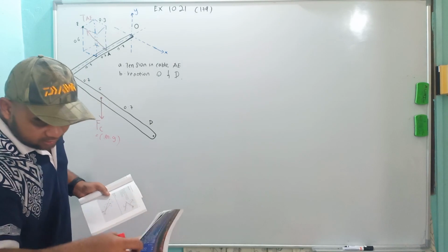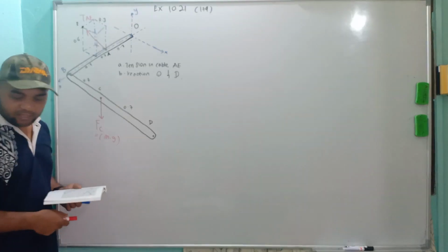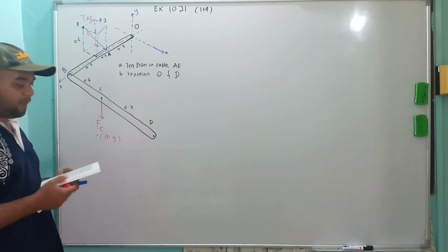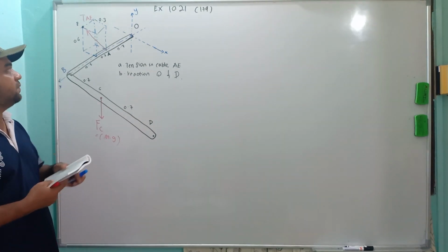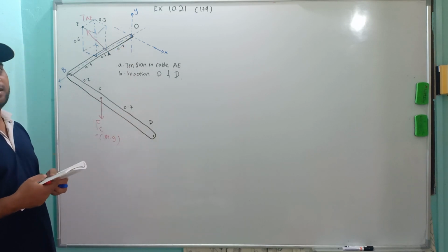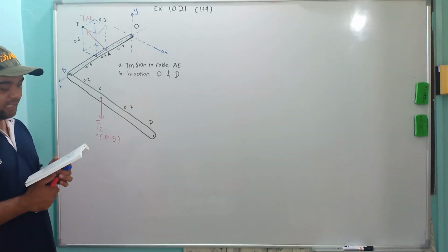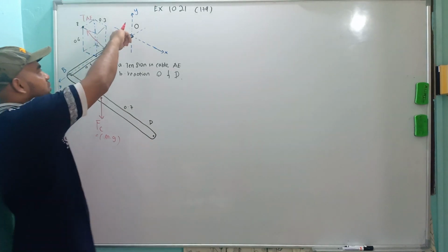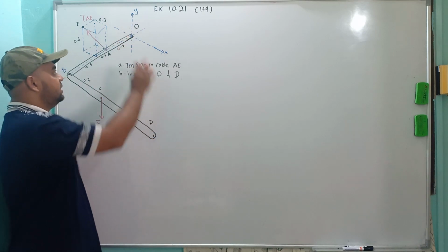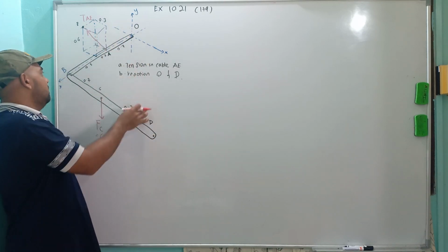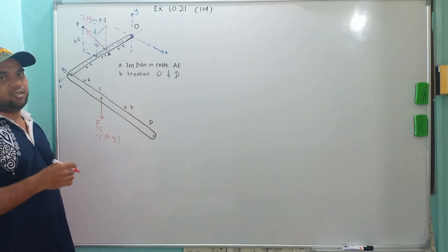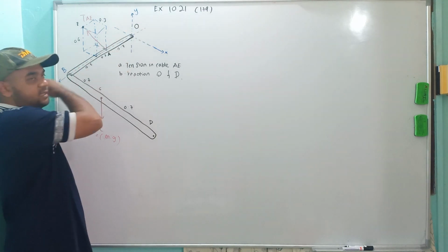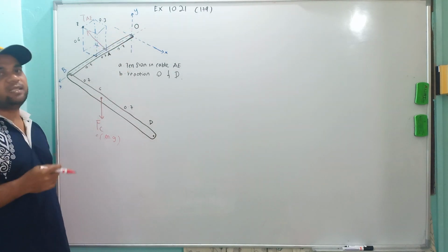We should go to the reaction forces now. We have two parts that support this component: the first is O, the second is D. At O, it is a radial bearing, positioned this way, meaning it allows rotation about the Z axis. The radial is in the Z axis, so it also allows movement in the Z axis.